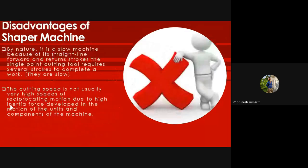A disadvantage of the shaper machine is that by nature it is a slow machine. You can see the video of it. It is a slow machine moving in forward and return strokes, at a lower speed, because of the straight line forward and return stroke. The single point cutting tool requires several strokes to complete a work, because it is a single point, not a multi point. So it requires a number of strokes, and it can be a slow process. The cutting speed is not usually very high because the high speed of reciprocating motion produces high inertial forces developed in the motion of the unit and the components of the machine.